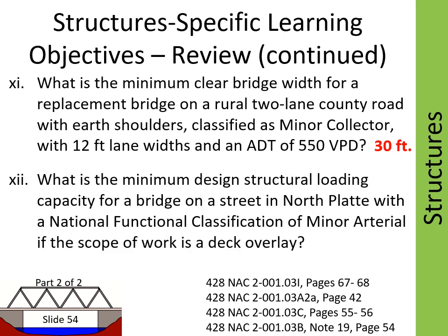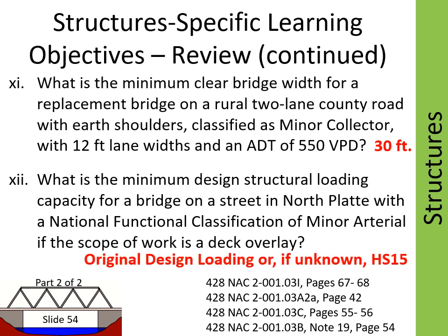Question 12. What is the minimum design structural loading capacity for a bridge on a street in North Platte with a national functional classification of minor arterial if the scope of work is a deck overlay? The answer is the original design loading, or if unknown, HS15.